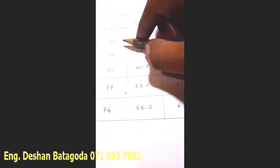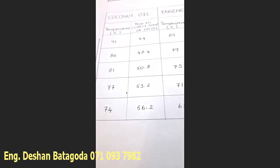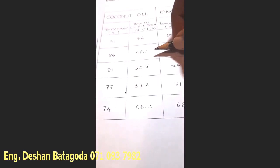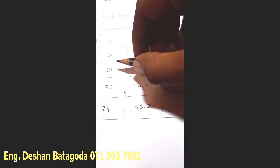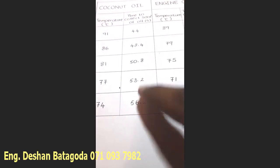Like that, we start this experiment at the highest possible temperature, right? Later, with respect to time, the temperature will drop down. Now the temperature is 86, then the time taken is 48.4 seconds. Got it? So like that, for 86, 81, 77, 74, we have recorded the time taken to collect 50 cubic centimeters of the oil.